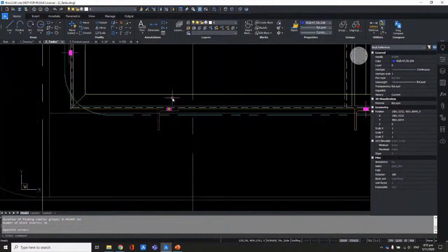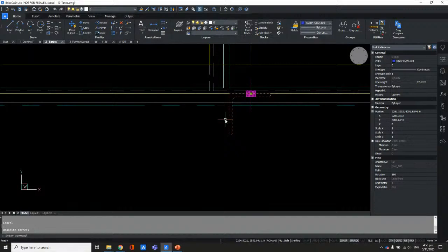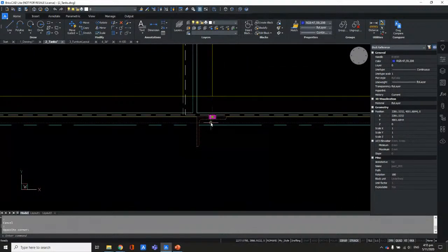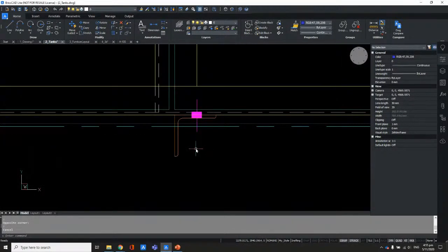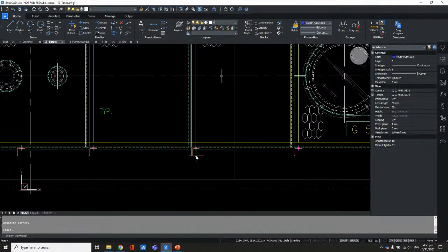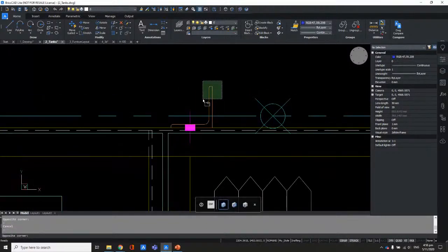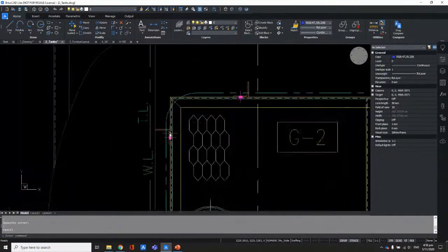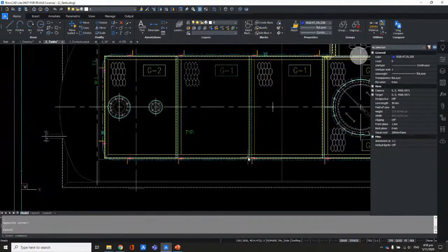So that's great. And what's more is that if we go here, it also correctly changed this other L bracket into a similar block. That's really good because we don't have to keep redoing this block or defining a block and then copying it out. So that's pretty good, I think. And what's more, it does Blockify correctly also with a different orientation and a different direction. See here, they're all jumbled up, right? But they all are now in the same block.